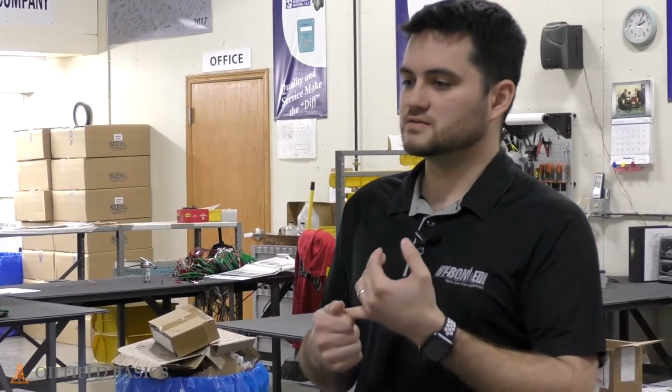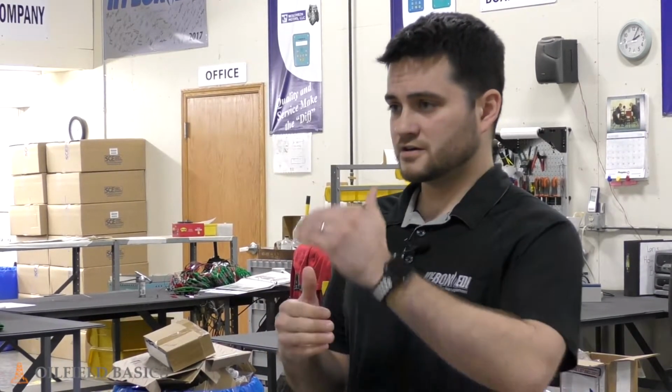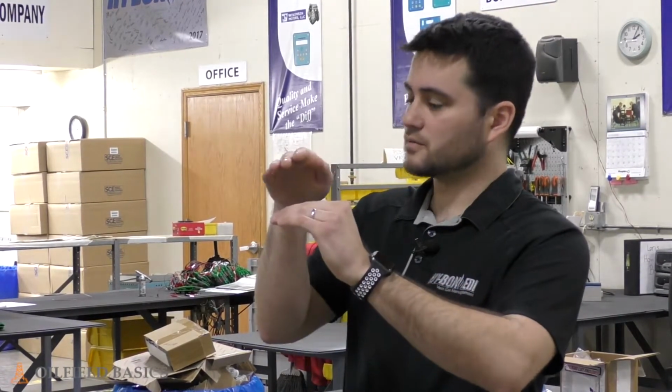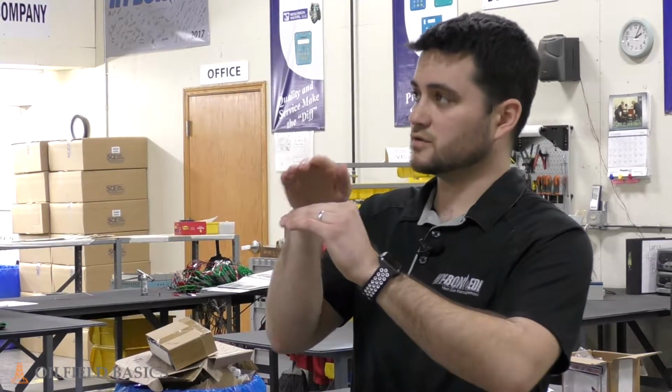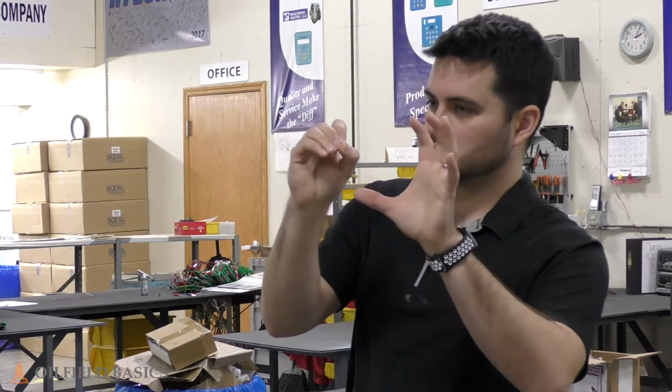The other way is UV sensing, and that's an effective way to do it as well. It's either there or it's not. Typically that kind of hardware is rather expensive. But that's another way to do it. And I didn't mention a third way, and that would be based on temperature. If there is a minimum temperature where, say, a thermocouple is sensing that flame where the pilot ought to be, then when it hits that minimum temperature that the control system is looking for, it will think that there's a pilot.